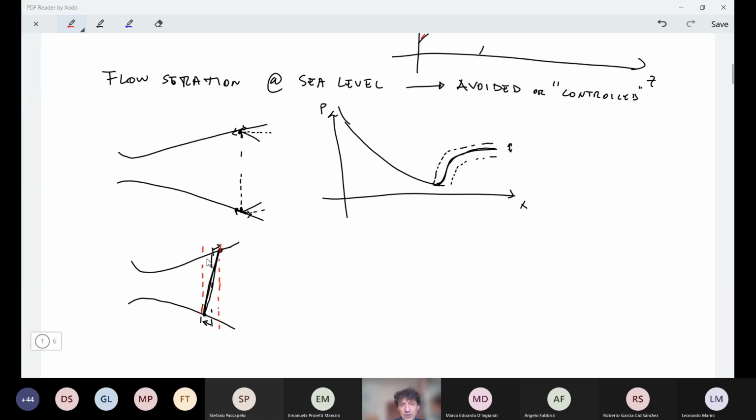So this will be less than half the pressure that we have on this other side. As a result, we have a resulting force in this direction, and we refer to these forces as side loads. This will also be a bending force that will act on the nozzle.